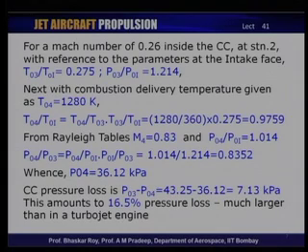Now, this amounts to 16.5% pressure loss, and as you are aware of the kind of pressure loss that is normally prescribed in turbojet or turbofan engines, this pressure loss is very high compared to those pressure losses, where they are normally of the order of 3 to 5%. Here it is 16.5%. So, the pressure loss in typical ramjets could be somewhat of a higher order than the turbojets and turbofans that we have done before.